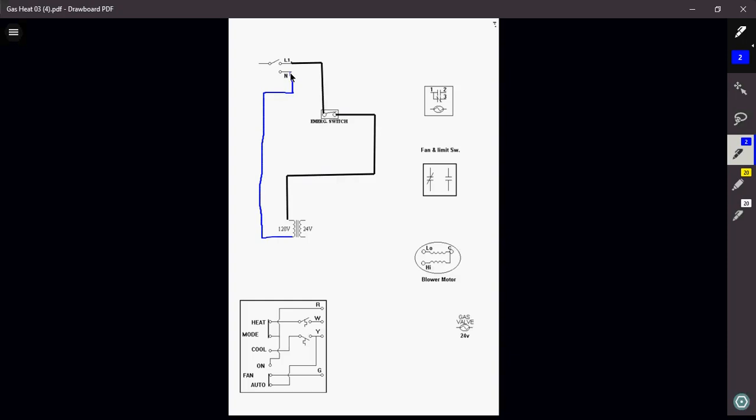Okay. Remember, on any circuit that is out there, we got to have a source, a switch, a path, and a load. We already have that one basic circuit right there. Okay, here's my source, my path, here's my switch, and the primary side of my transformer is my load. Okay, so where else do I need to go to finish my 120 volt side of this diagram?